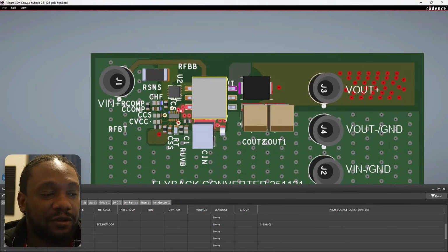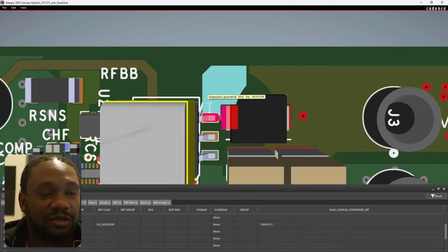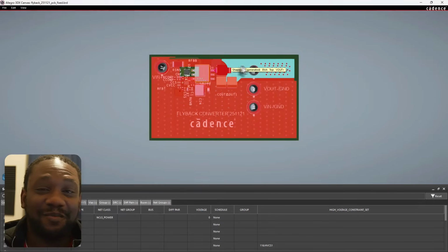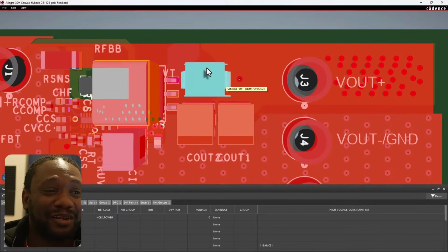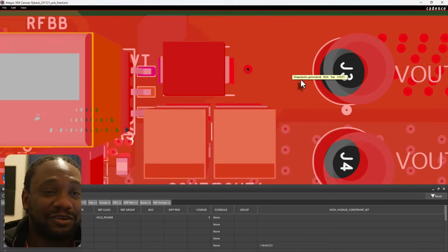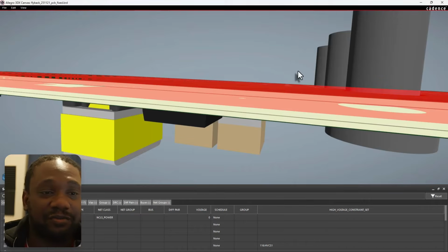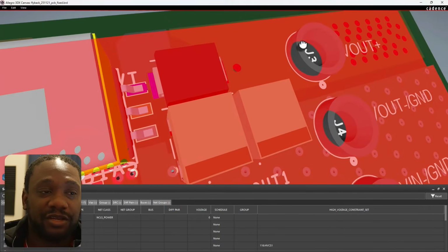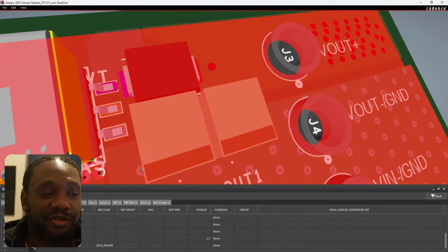We have the hot loop coming right off the secondary side of that transformer. Underneath here, I need a return path. So see, my return path is everywhere on the PCB where I can put it, essentially. So I've got return all underneath on the second layer, or ground if you want to call it, really it's the return path. On the second and third layers underneath that hot loop area over here, underneath my V out. Let me show you my V out.